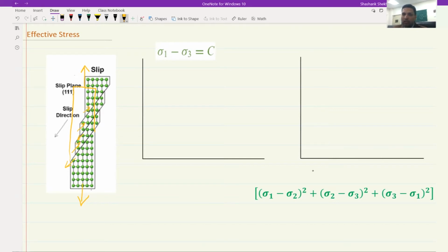But when the shear stress at a particular plane exceeds a critical value, there has to be shearing, and there will be slip, and there will be deformation, which again we will understand later when we get to the concept of dislocations. So for now it is sufficient to understand that deformation occurs by movement of dislocations and not by complete tearing of atomic bonds, and hence normal stresses are not as important. But shear stresses are critical. Okay, so that is the first part.